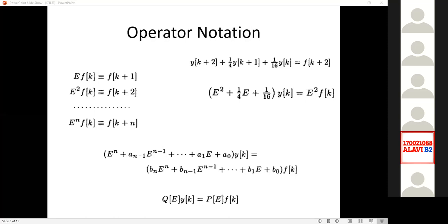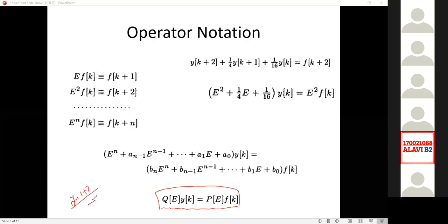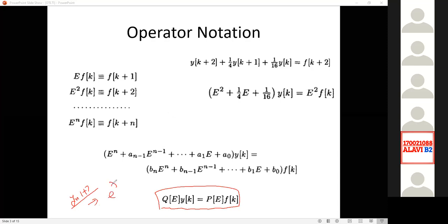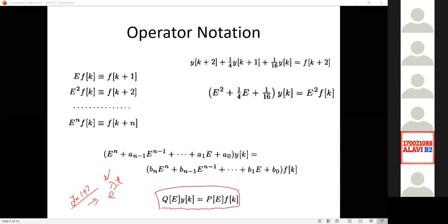With this, what we have obtained is that the homogeneous solution or natural solution y_n(t) in the case of continuous time takes a general form e to the power lambda t, isn't it? That is the characteristic root. Depending on the order of your system, the number of roots will vary. For a stable system, your lambda will have a negative real value.